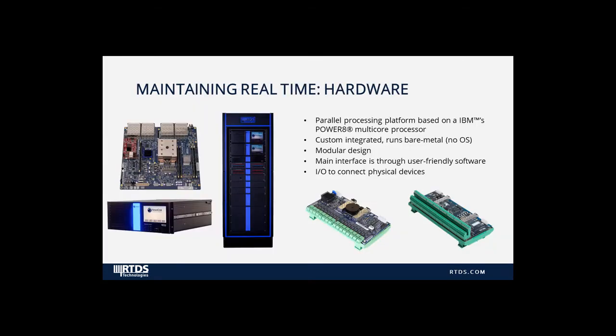Running a real-time EMT simulation is a very computationally intensive process, and it can't be achieved on a standard PC. So the RTDS simulator is built on dedicated parallel processing hardware, specifically integrated for the real-time simulation application. Our current hardware generation is called NovaCor, and it's based on IBM's Power8 multi-core processor. So when the demonstration runs later, you'll see the software side of things on Dr. DeCordy's PC, but not the specialized hardware that the executable code is actually running on, and it looks like this.